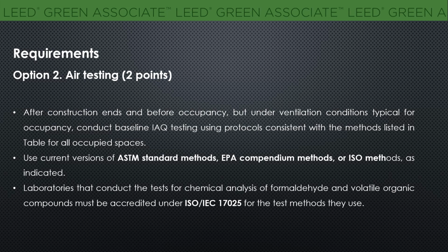Laboratories that conduct the tests for chemical analysis of formaldehyde and volatile organic compounds must be accredited under ISO/IEC 17025 for the test method they use. And for retail projects, they must conduct the testing within 40 days of occupancy. And I will explain the table.